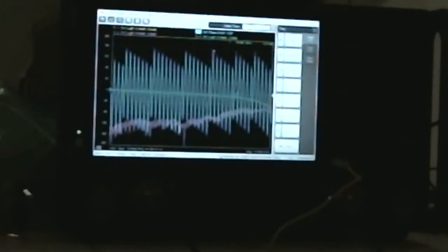you don't want to just say, okay, the antenna has 15 dB return loss. That's good, but you don't just care about VSWR. You'd like to also know what the exact impedance is on the Smith chart. Where is this, so I can match it better? Well, guess what? If you have bad phase issues, you're never going to be able to do your matching correctly. So this is why you need to have really, really good phase stability in your cables.